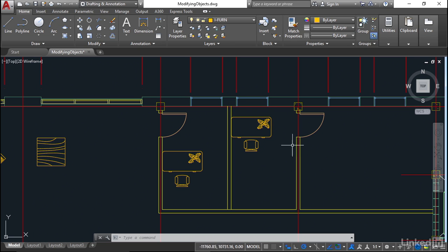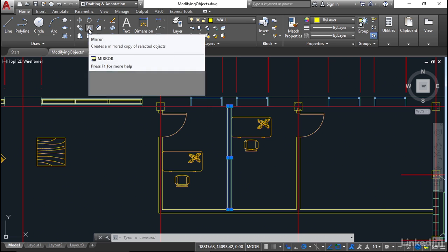What we need is also an internal wall over here in this office. So I'm going to mirror the wall I've created over here. I select the two lines, like so. The Mirror command is not on the shortcut menu, but AutoCAD by default is set to noun verb selection. Noun being an object, verb being a doing word, which means you can select the object first and then the command. I've selected the two lines that represent the wall, and I go up to the Modify panel on the Home tab on the ribbon. There's the Mirror command, and I select it.